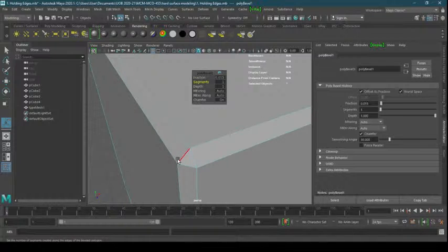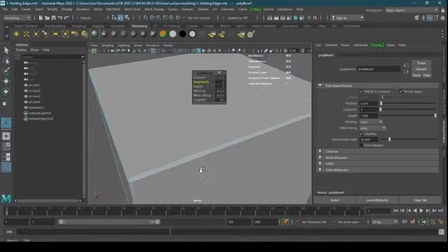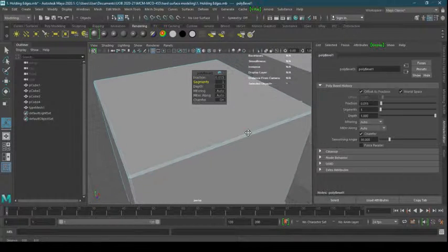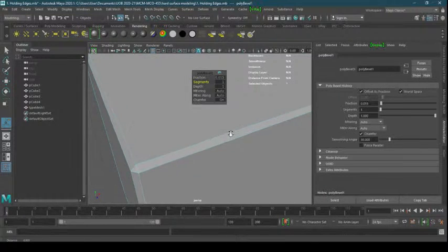And in hard surface modeling, all your faces, what are these? These are faces, right? This is a face, this is a face, this is a face. Here, this is a triangle. All the faces in hard surface modeling, or any kind of modeling, should be square. Square means quads. Quads mean 4 points, not tris. Tri means 3 points. They should not have 3 points.